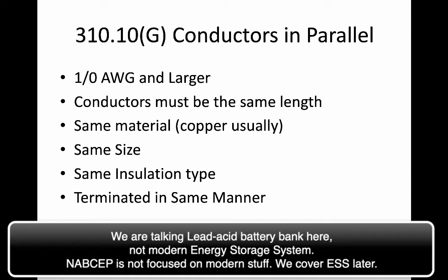And so when we talk more about batteries later, we're going to be learning about why it's better to have a single string of batteries and why 2-volt lead acid batteries are a lot more popular than 12-volt lead acid batteries for large battery systems. Because if you were going to have a 48-volt system, you could go 4 12-volt batteries, or you could go 24 2-volt batteries. And if all the batteries were the same size, then you're going to get a lot more power out of a single string with 2-volt lead acid batteries.